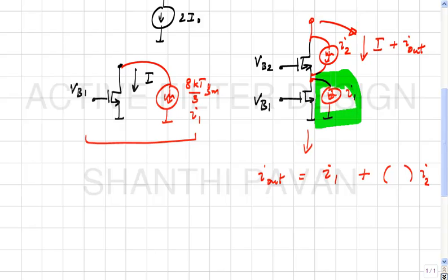So please note that as far as this current source is concerned, right, it sees two impedances. One is the input impedance of the common gate device above. The other impedance is the RDS or the GDS of the lower transistor. This current will simply split in the ratio of those two conductances, right? And almost all of it will go through the top transistor, simply because the input impedance looking there is 1 over GM, whereas the impedance looking below is RO, and we know that for a transistor operating in saturation, GM-RO is a large number, correct?